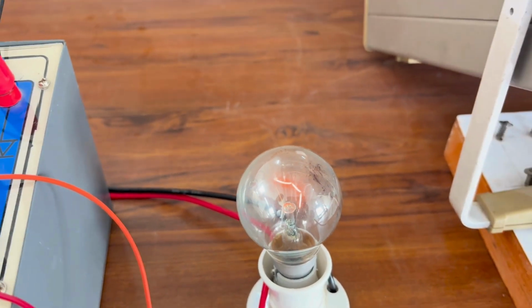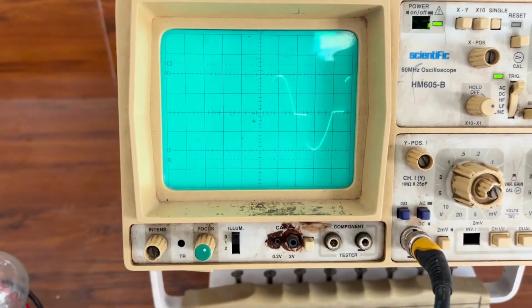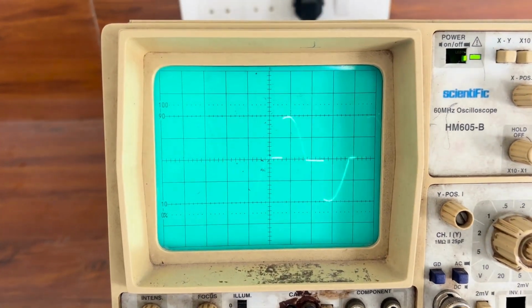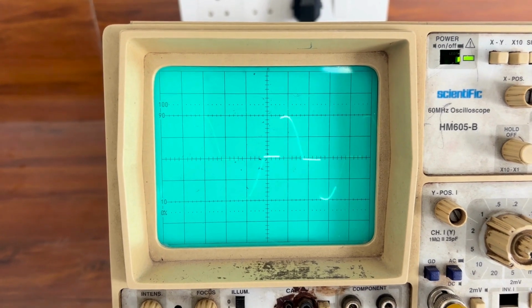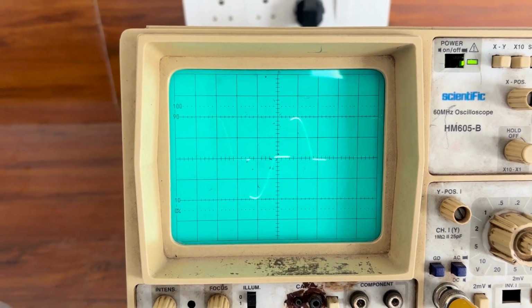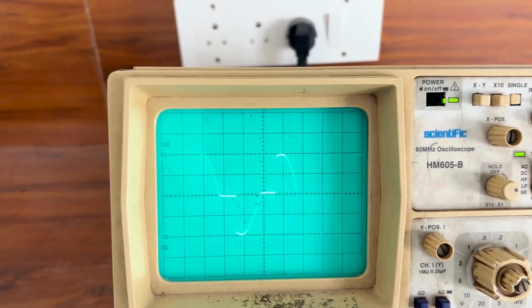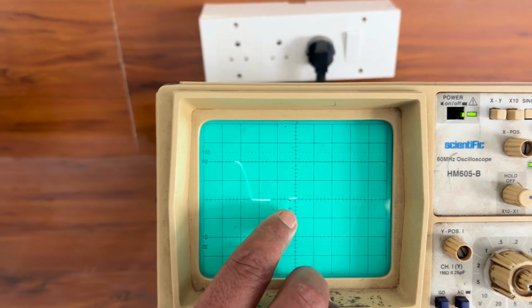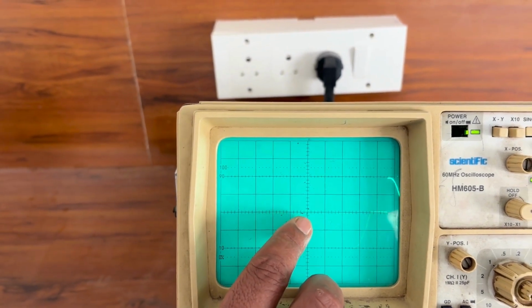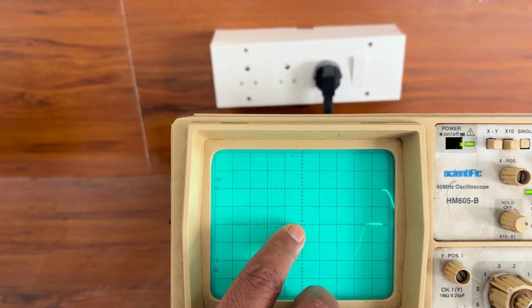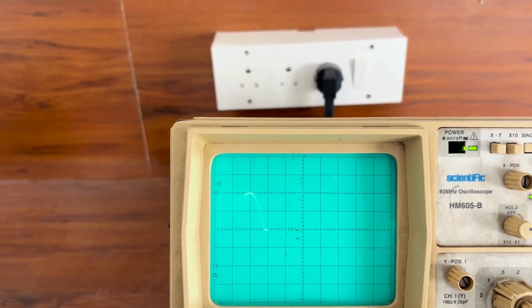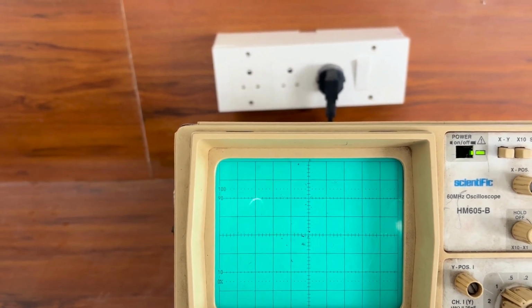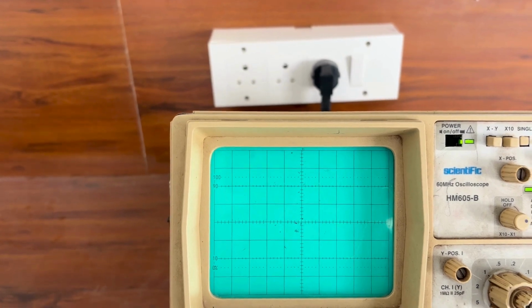Hence we can also observe the waveform across the CRO. In the CRO, when I vary from maximum to minimum position, a firing angle alpha occurs. So we have to calculate the number of divisions. As the pot is varied, we need to check how many divisions have been crossed. That is nothing but the firing angle alpha. So let us go for the calculations. We'll go for one calculation.